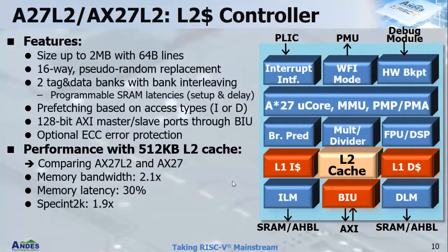Why should we add an L2 cache? If you're running an operating system especially, an L2 cache will increase your memory bandwidth by a factor of 2.1, and the latency will decrease by 30%. That means if you're running, for example, a benchmark like SpecInt 2K, adding an L2 cache will increase your total performance by almost a factor of 2.